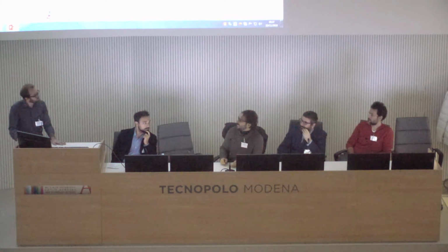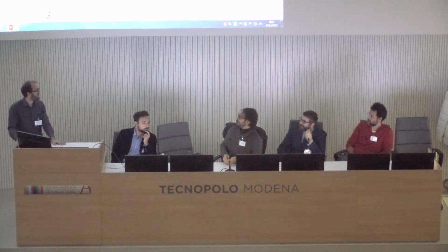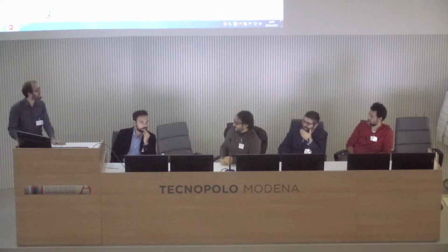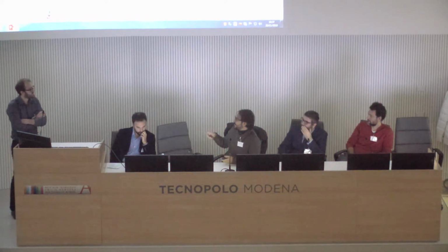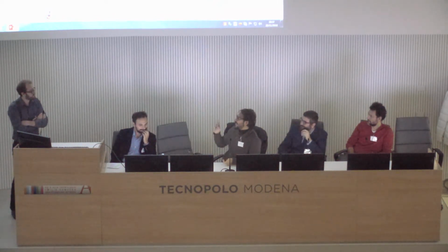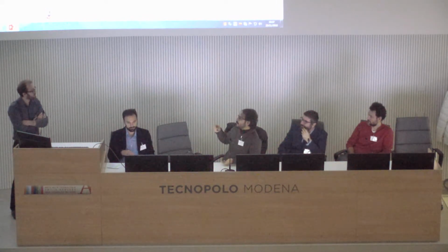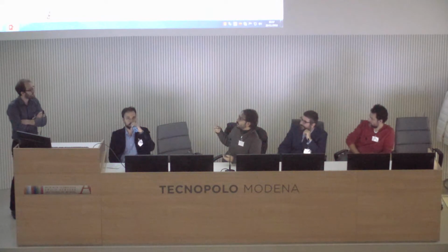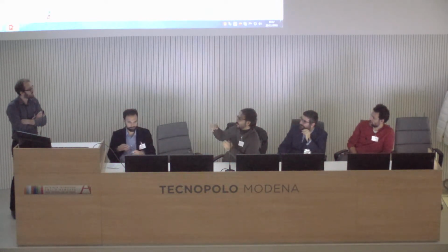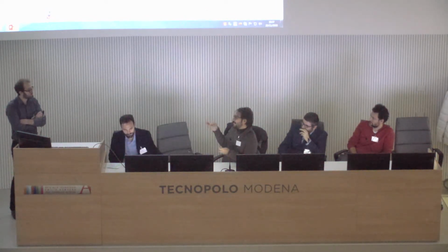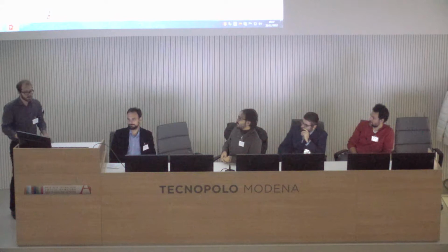Another question is a user interface improvement. In working with beams, one of the main problems when you create a model is to check that your beam section is oriented correctly in space. Let's say a double T or IPE beam. Is there planning in the development to have a sketched section in the three-dimensional view of a structure, in which you can analyze and check the orientation of all the beams?